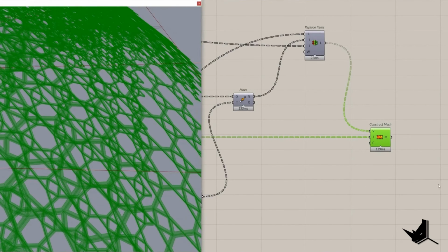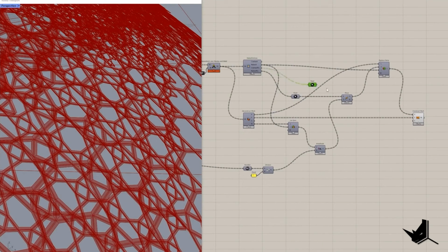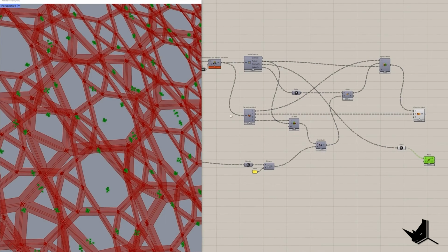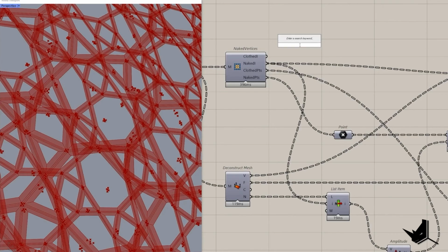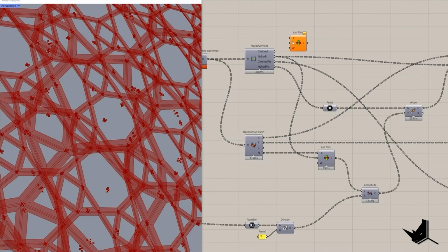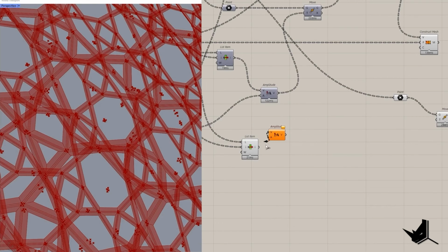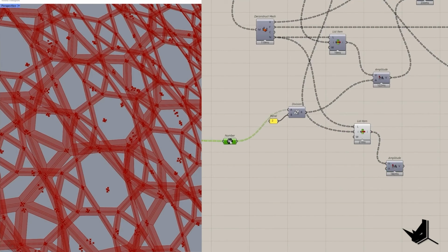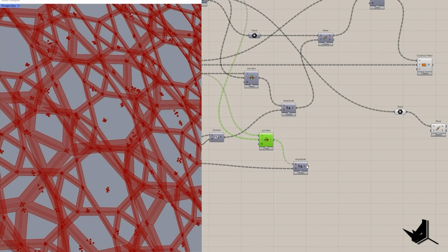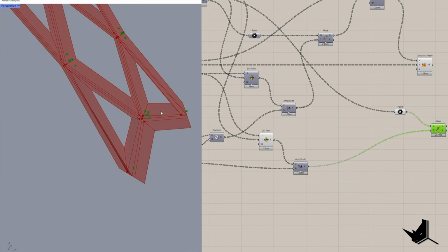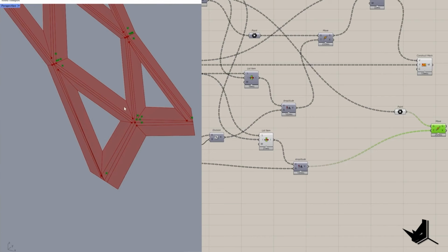Now we need to create the upper part of the mesh, which will be, if we take the closed vertices, these guys, and I want to move them along the normal direction, but we need to take only the normal direction of the clothed vertices. Here we have their index value. So here is the index, here we have the normals, and we need to create the amplitude. Amplitude now will be the height, so it will not be divided by 2, and I'm going to place it. All right, now we get the position of the inner vertices moved along the normal direction by the full thickness of